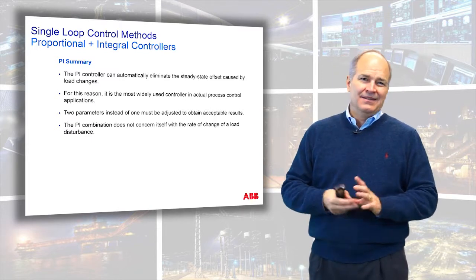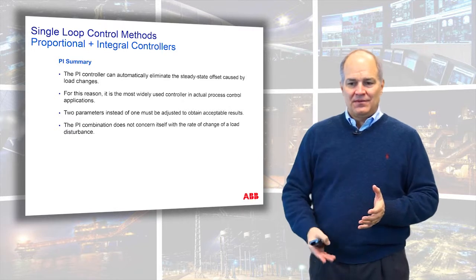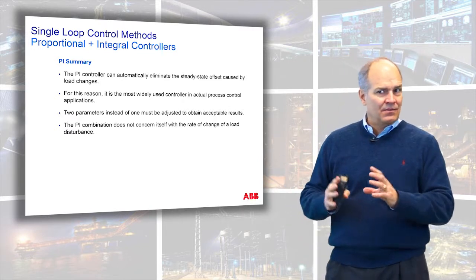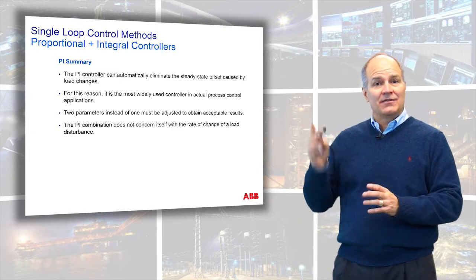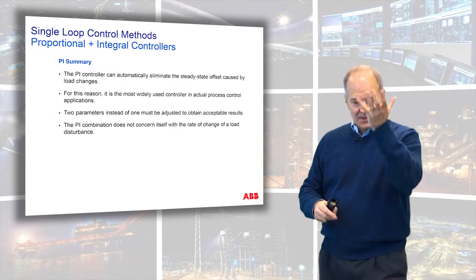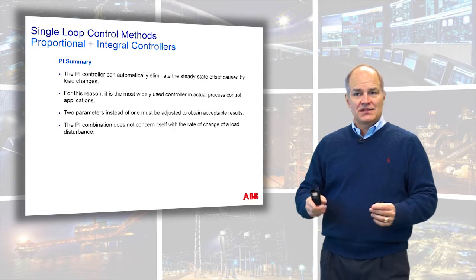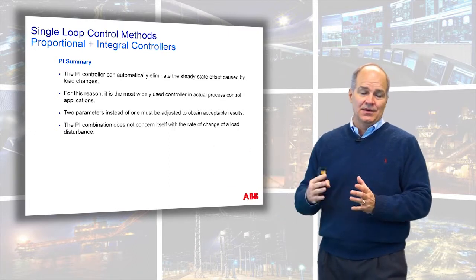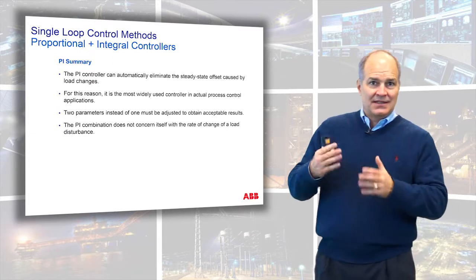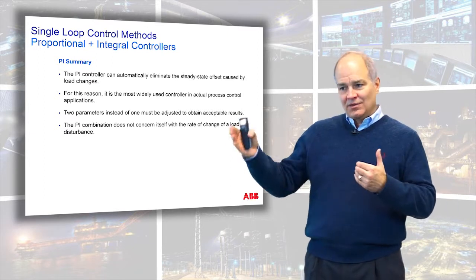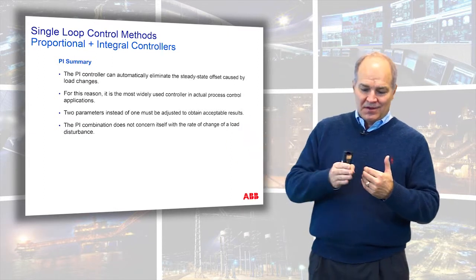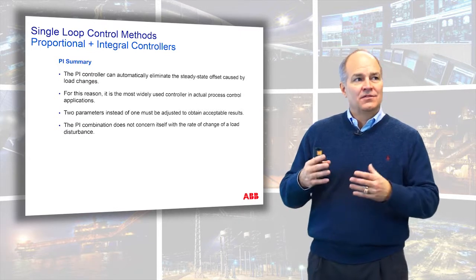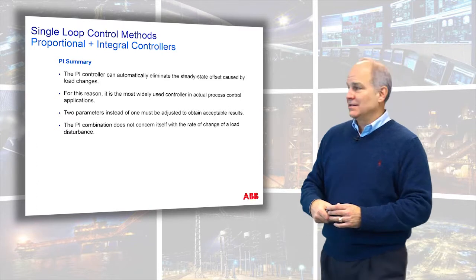Matter of fact, a lot of times I'll look at derivative, and if they have values in derivative, I really question why they have so many. It's usually a red flag. So a lot of times I'll dump all the tuning parameters out of a system and I'll look and see how many derivative. And especially if the derivative is a big number, because of the noise in today's systems, what's happening is the derivative number gets smaller and smaller and smaller until its effectiveness drops. So those are indicators of the tuning methodologies that these places use.